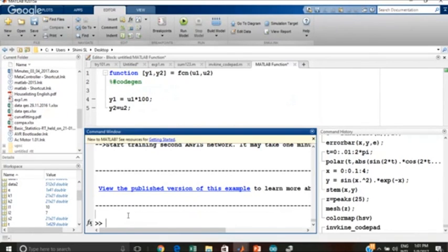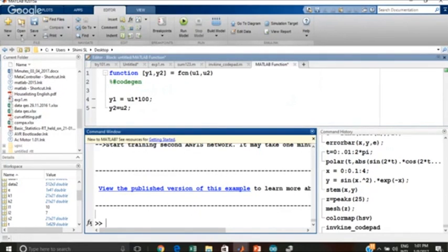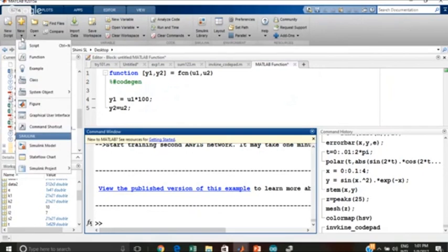I'll just show you. We are just going to create a graphical user interface. Till now I showed you the coding as well as Simulink, but graphical user interface I didn't show because I just wanted to show it here. So for graphical user interface, you can just go to Home. In Home, New. Okay, in Home, New, if you go, you have graphical user interface. One option is here. Or you can just go and put guide in the command window. Guide. That is the command.